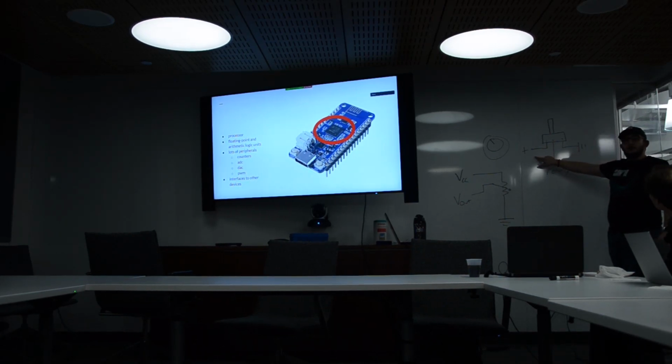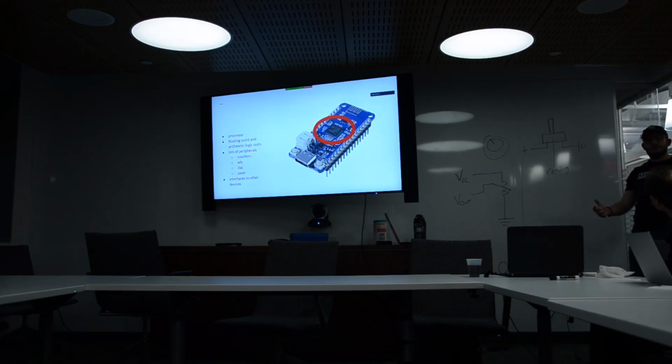So what you do is you read, because there are 3 contacts inside. One contact is at the front of the coil, one contact is at the other side of the coil, and then the last contact is on a wiper that can move around. So it's an arm that's touching the coil at different spots. Depending on how far down the coil you touch, the higher the resistance you see, so the lower the voltage you see. Does that make sense?